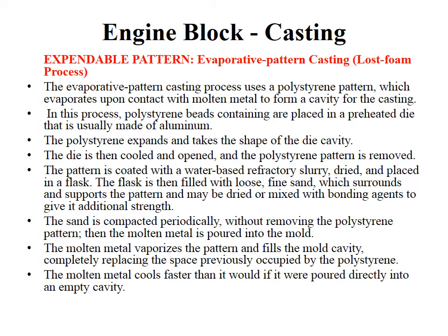So expendable pattern is the pattern which itself will be destroyed when the metal is poured into it. So that is why it is known as evaporative pattern. So you keep a replica of the casting product which you desire, which is nothing but the pattern, and that pattern will evaporate, and this casting is also known as evaporative casting or lost foam process. So what we use is nothing but polystyrene pattern, and that will basically evaporate when it comes in contact with the molten metal that is poured into the cavity for the casting process.